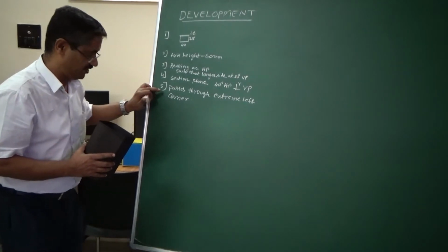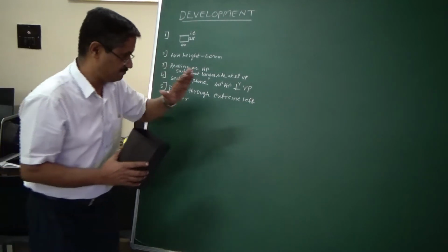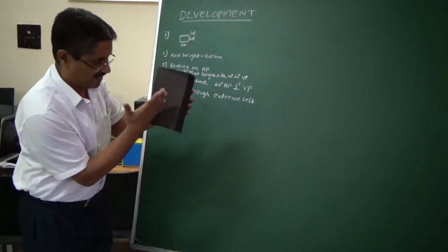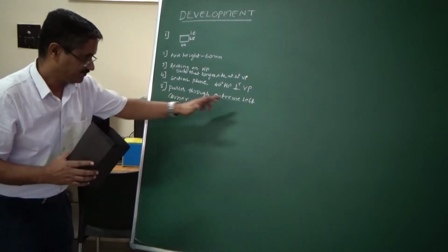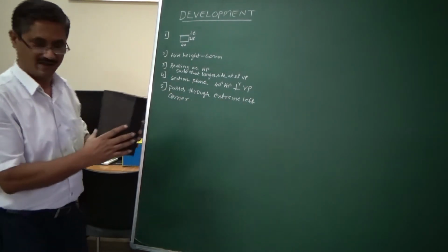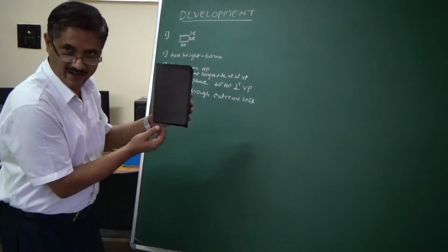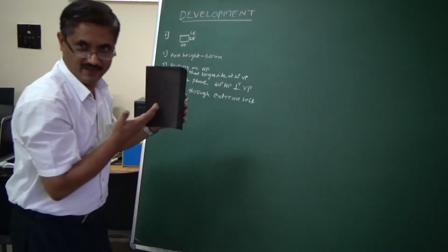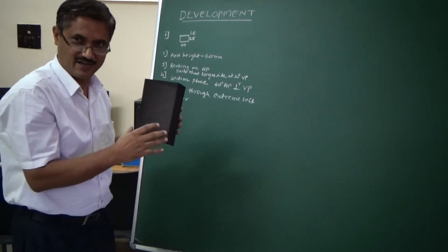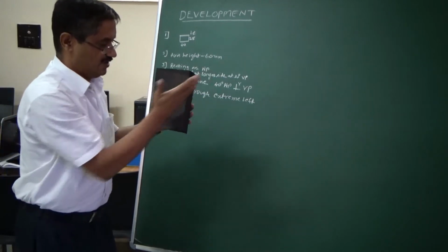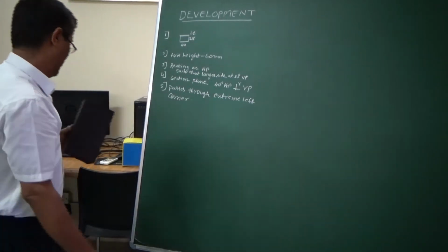Further, you look at where it is cutting, whether the section plane is passing through the mid height or at a corner. In this case, it passes through the extreme left corner. When we say extreme left corner, this is the corner, so from here it will be cut. When I cut like this, I will show the cut section development afterwards. This portion remains, and that is what we are trying to develop.